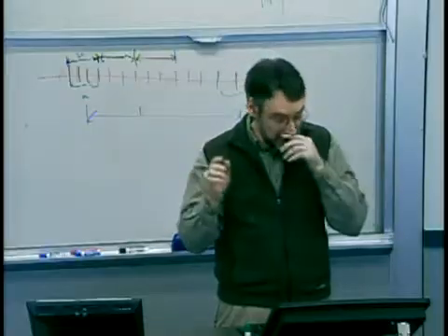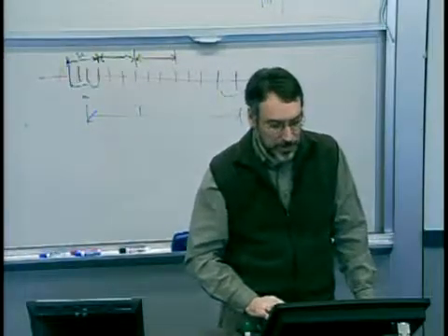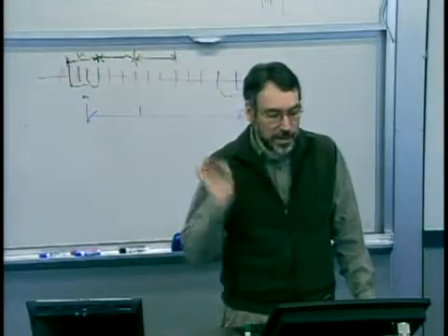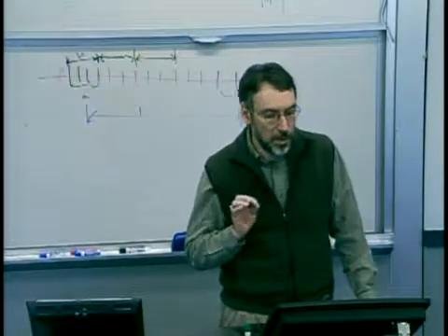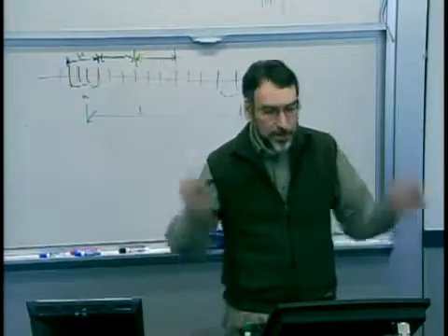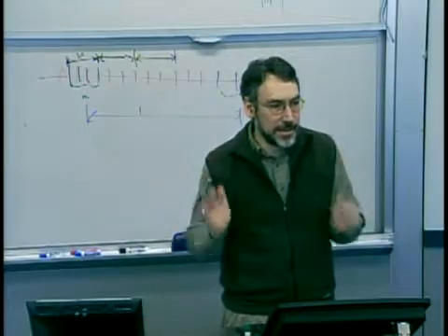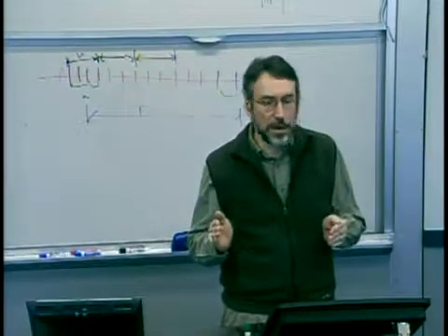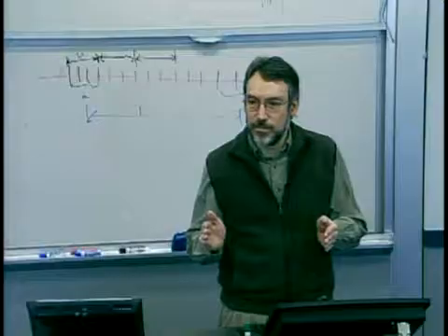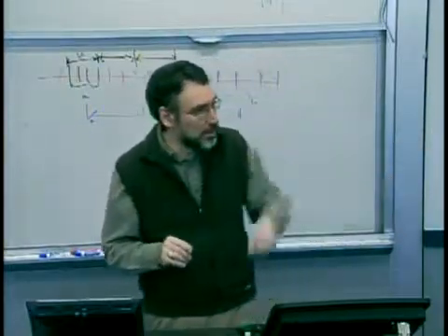Then Cpk, as we'll see in a minute, also pulls in the idea of the mean difference. First off, the definition of Cp, or process capability ratio, is simply the distance between your upper and lower spec limits over 6 sigma of your underlying process. Now you start to hear the six sigma kinds of terminology.